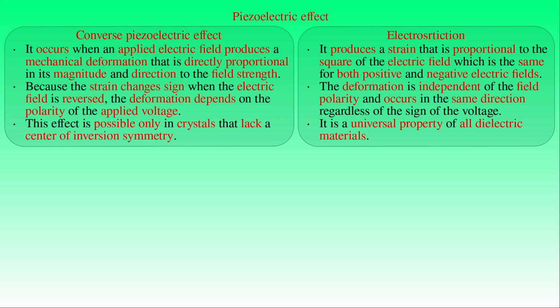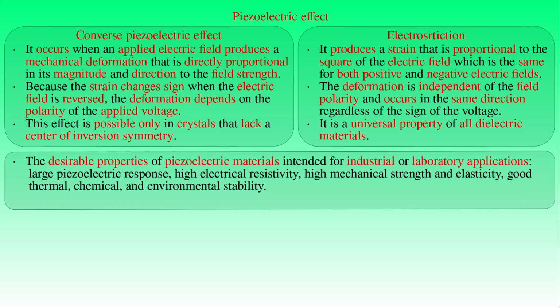In practice, piezoelectric materials intended for industrial or laboratory applications should possess several desirable properties. They should exhibit a large piezoelectric response, generating a significant electrical signal from a given mechanical stress or a substantial mechanical deformation under an applied electric field. In addition, they should have high electrical resistivity to prevent the charges generated by the piezoelectric effect from leaking away.